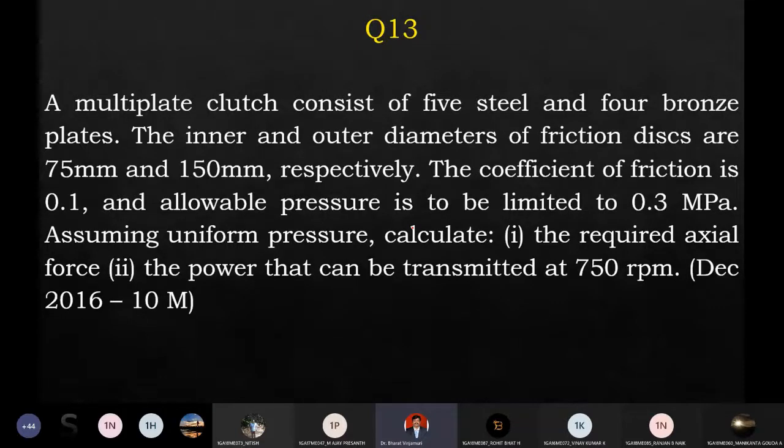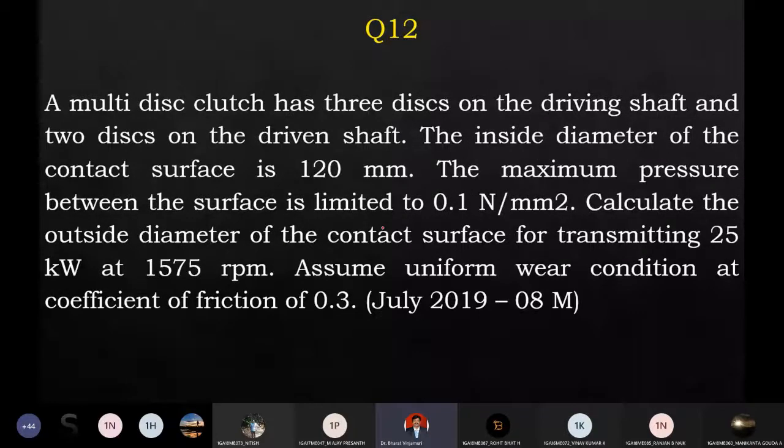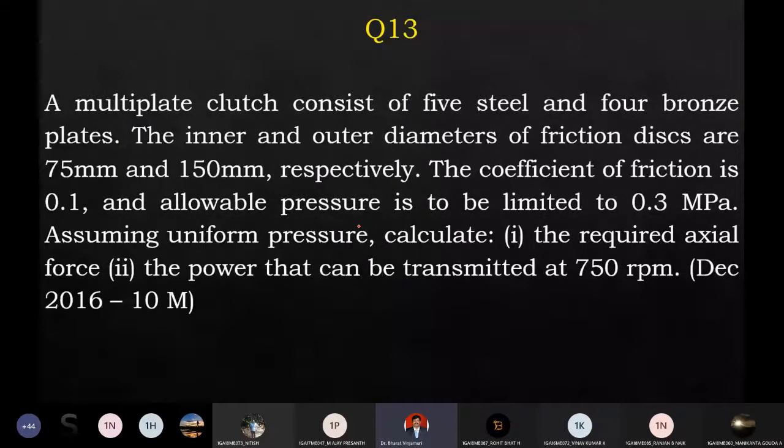You remember the diaphragm spring. The diaphragm spring has another name, Belleville spring. Sometimes compression springs are used. Now, how do I calculate the dimensions of the spring? By using this value of FA from the clutch. So always remember this: since it is a transmission system, links have been given everywhere, so FA will be used. We will try to use FA in springs. So this is what exactly we will be trying to do. Any other questions you can ask me now.